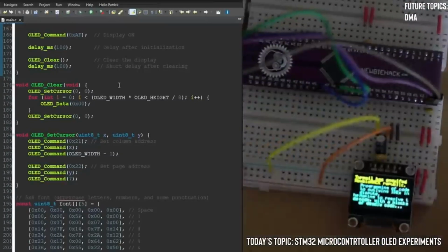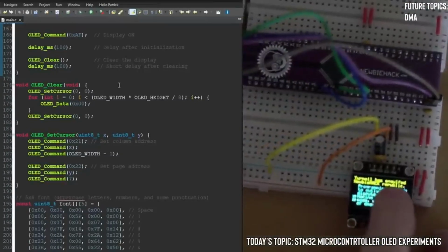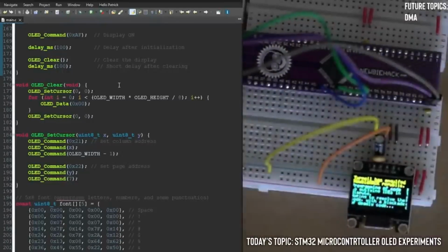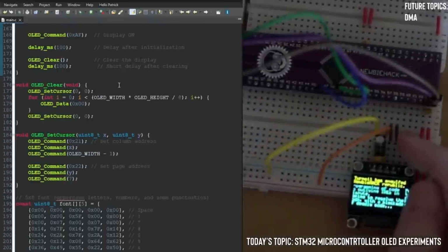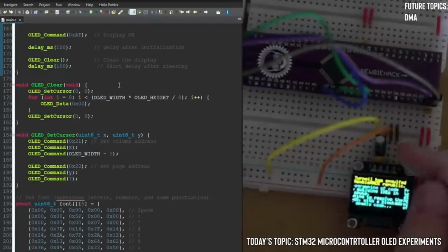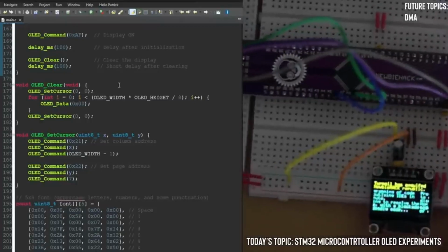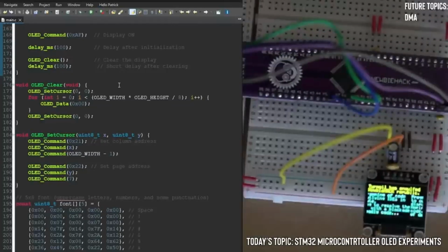That's it. And on the OLED circuit, there's a 0.1 uF and a 100 uF capacitor, just to help the circuit filter anything because of this very offending breadboard setup I have. What's the problem? Oh, because I don't have a reset? Yeah. And I could probably set that up maybe next time. Maybe I'll do a reset circuit on the next live stream. Okay, cool. Yeah.